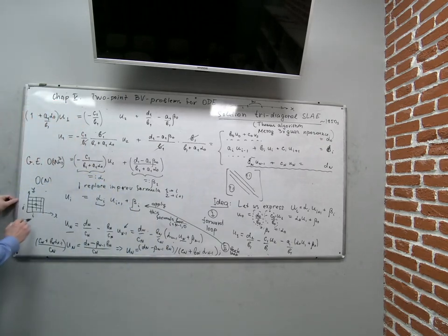But in modern problems, people very often consider complex computational domains. And for such complex domains, building a mesh of this kind becomes a very tricky, separate problem. It is still possible if you divide the area into sub-blocks, which are topologically equivalent to a square, and then divide each block with a regular mesh.